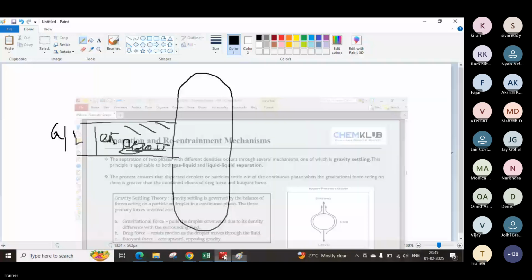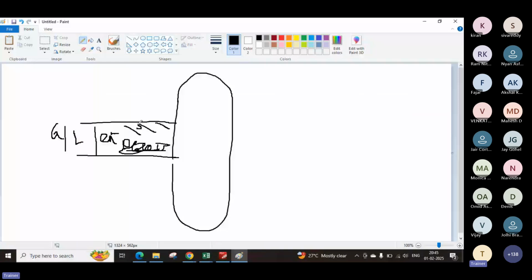Once this comes in, there are some small particles of liquid which may be flowing in this zone as well. Because we are assuming these are at equilibrium, any pressure reduction will lead to any trapped gas going into the vapor phase, because of the change in saturation or to match the enthalpy balance. So when these particles come inside the separator, suppose this is a circular one.